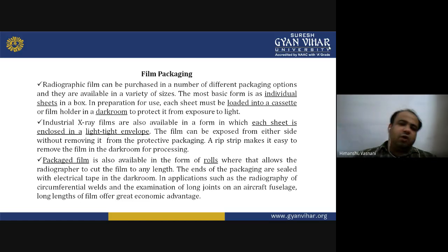The ends of the packaging are sealed with electrical tape in the darkroom. In applications such as radiography of circumferential welds and the examination of long joints on an aircraft fuselage, long lengths of film offer great economic advantage. So this is film packaging.